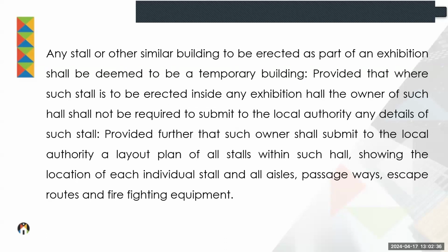Then we come to stalls or similar buildings to be erected as part of an exhibition. That can also be deemed as a temporary building. So if you're going to have a show or a church bazaar or something, and you're going to put up stalls, remember that a plan needs to be submitted showing aisles, passageways, escape routes, and firefighting equipment for the duration of that use.